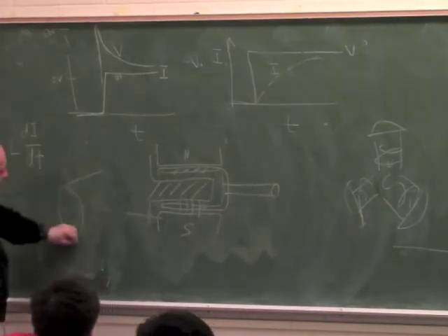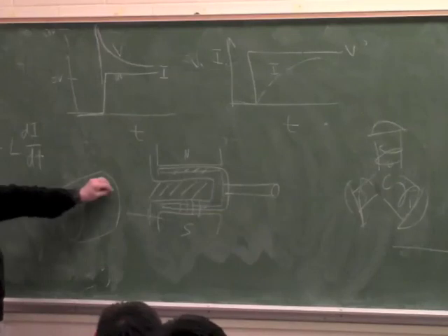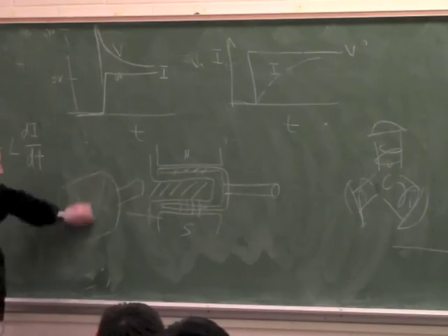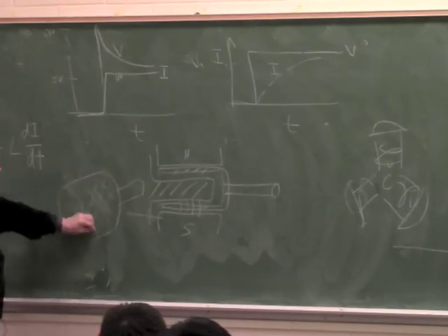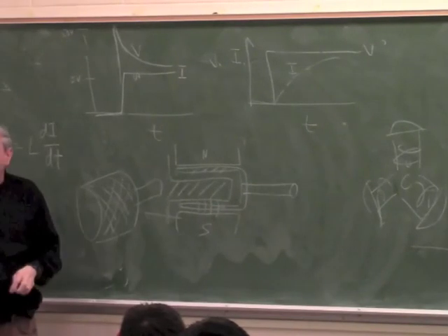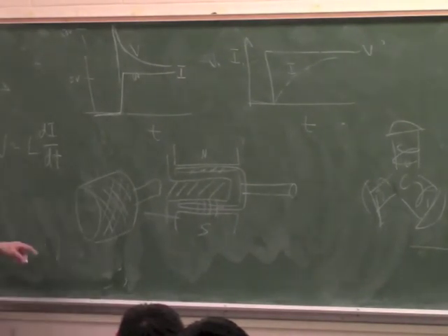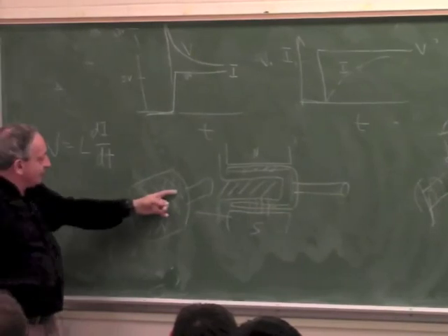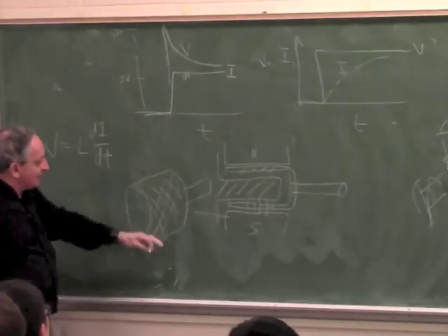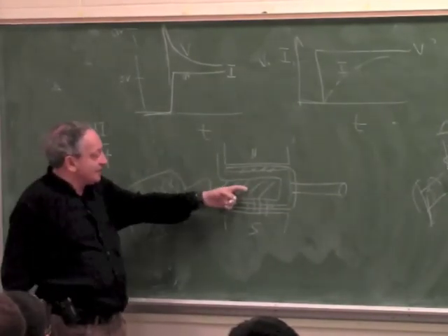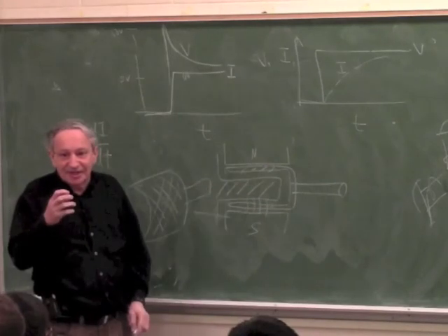The rotor looks exactly like a cup, open from this side and has a shaft. And it's wound with wire and epoxy to be self-supporting. Okay, now inside here you either put a piece of steel or a magnet, and outside you put a magnet. Most of these motors are reversed. The magnet is inside just to minimize size.